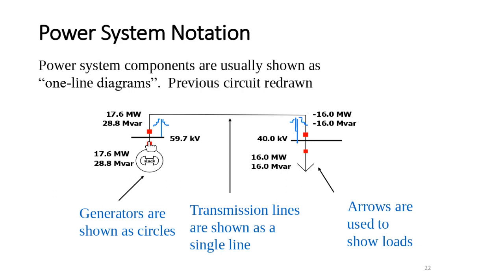Then what we have is what we call a leading power factor. When the generator absorbs reactive power, we call it a leading power factor. In other words, if the load is producing reactive power, it is a leading power factor. When the generator is producing reactive power, it is a lagging power factor. So you need to know the convention